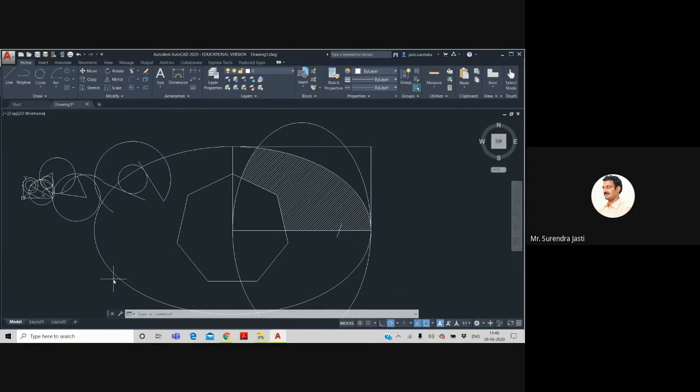Is it for representing a sectioned surface? When the object is cut by using a section plane, to represent the cut portion we use these hatching lines. And these ANSI codes depend on the material: there are various sectioning lines for metals, for wood surface, glass surface, like this.